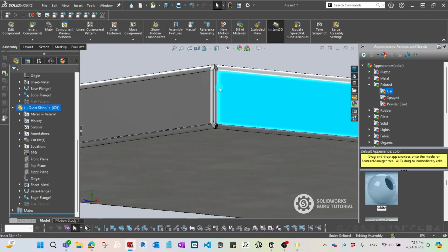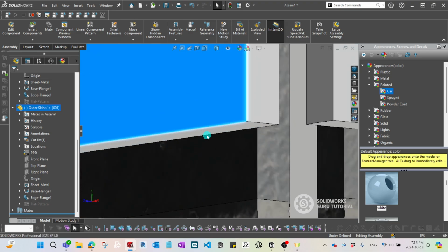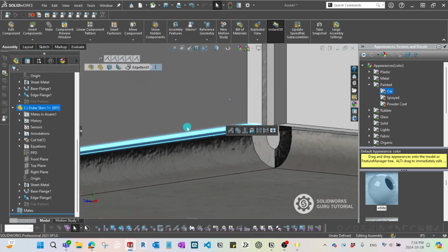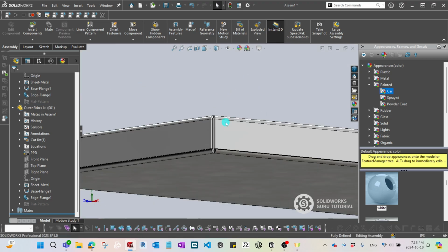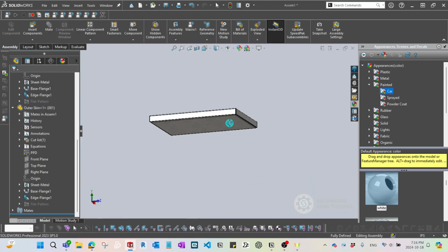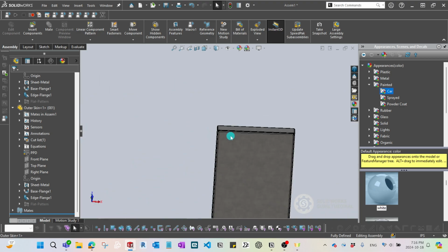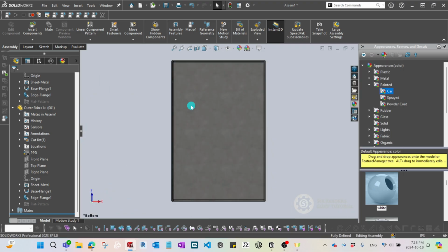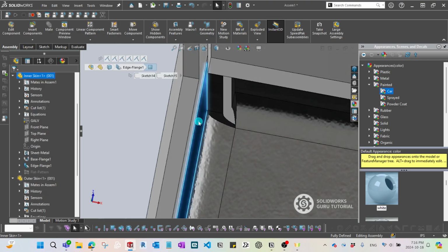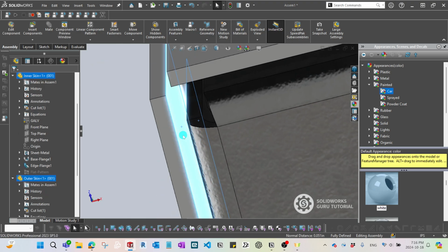So the way you can assemble is you can provide a bit of gap, but you can assign line to line, and then it's definitely going to be a much cleaner fit. So we can create perfect fits. We can look at it from the bottom side to see how those fits are working. So yeah, you can see there's a bit of gap, as you can see, 0.051.